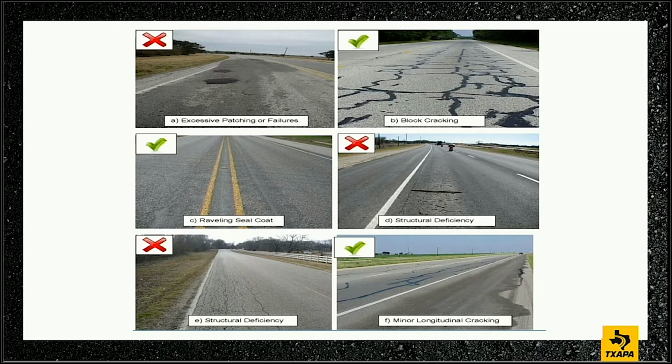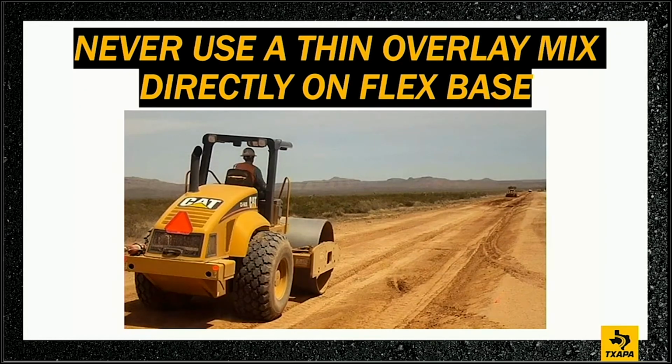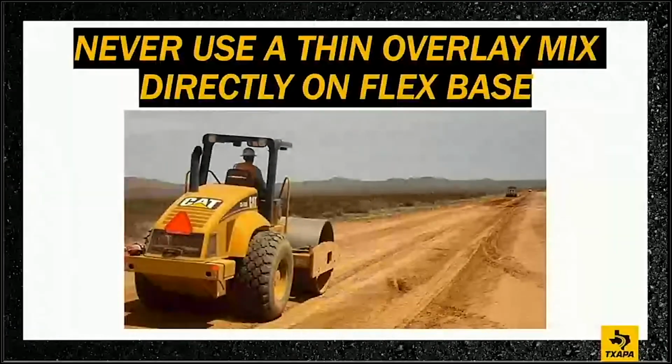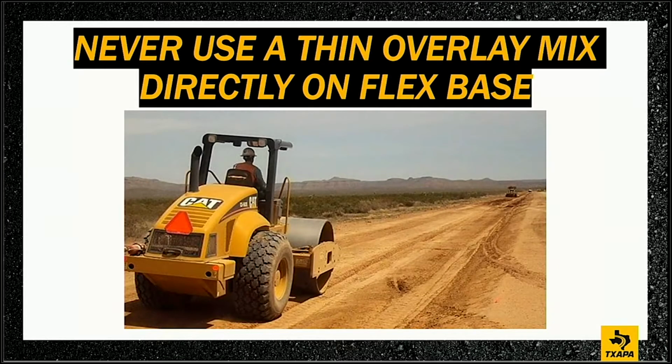And the pictures that you've got, the X's up there, show, hey, it's gone too far for this kind of mix, or let's go in and fix it first, and then we can put this over the top. Absolutely, that's exactly right. We definitely need tests to determine whether or not it's going to hold up. We have ground penetrating radar, we have falling weight deflectometer, and then we have the visual test. I think we're all attuned to the visual test, which tells us not to put it on those structural deficiencies. And here's a big one, guys: don't ever put it directly on flex base. You'll have a failure immediately, okay?